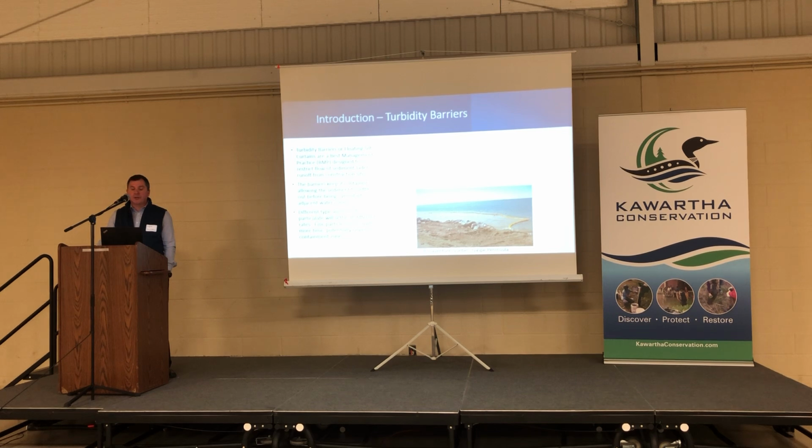So understanding the type of sediment that you're dealing with on site will help you identify the area, the size of containment required, and the proper installation of these barriers. The picture on the bottom right-hand corner here is a project that we did a few years back in the Gaspé Peninsula, Quebec. And as you can see, the barrier is doing a really effective job of sediment containment within that area. And that's ideally the goal that we're looking for here.